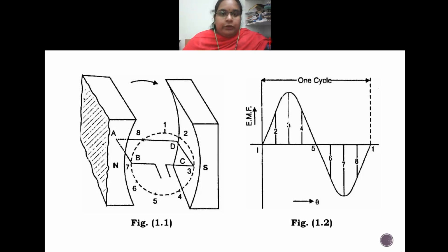So instead of going for the homopolar construction, in this heteropolar construction itself, we are going to introduce a small device called a commutator, which makes sure that the current collected by one of the rings is in one direction. Let us see how this is happening.